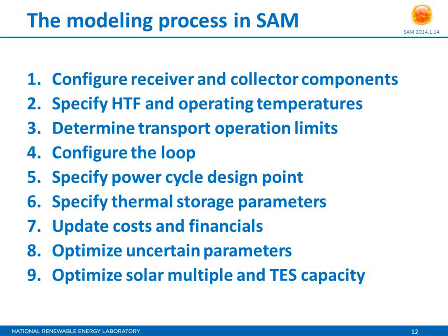Any new case that you set up should have some level of optimization, even if it's just looking at one parameter at a time, to understand how the performance and cost of the system depend on those parameters that you don't necessarily have a reason to set any particular way. And finally, for systems with thermal storage, it's always a good practice to optimize the level of thermal storage.